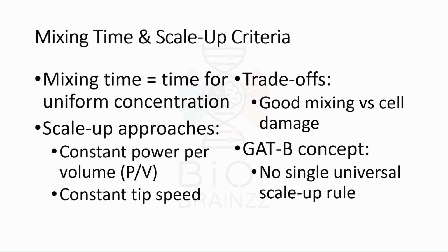Mixing time is the time required to make the system uniform. It is important for proper reactor performance. During scale-up, methods like constant power per volume or tip speed are used. There is always a balance between good mixing and cell safety.